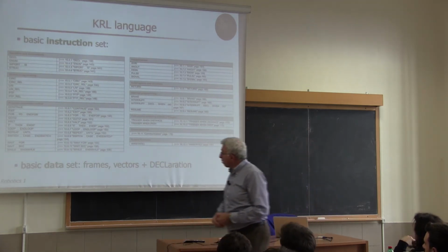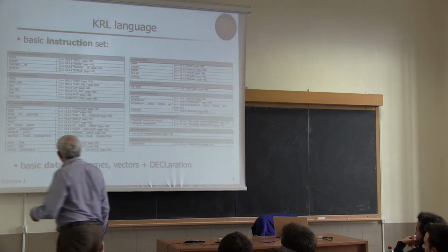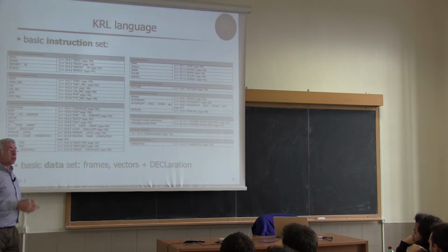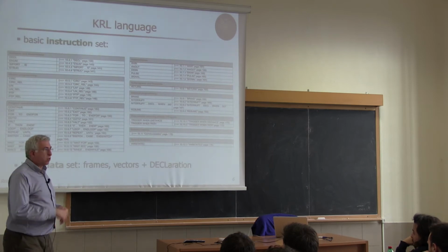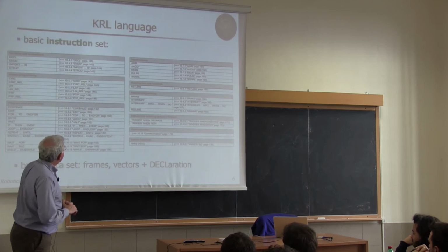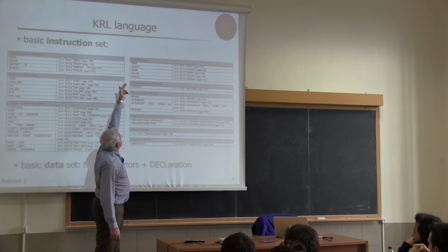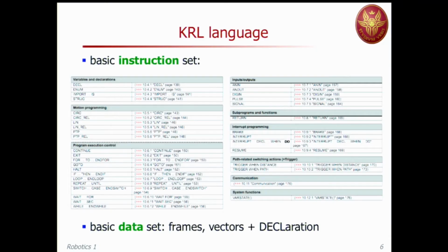Similarly, when you check and you switch your case, you may go and read some input ports or do something while writing on some output ports, so interfacing the robot with something outside. In fact, here you have inputs and outputs. You have typically analog input and analog output, or digital input, or the possibility of generating pulses or receiving pulses. For instance, pulses from encoders. Okay?